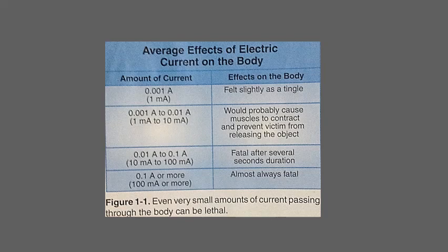Electrical shock. Electricity passing through a human body causes an electrical shock. The severity of a shock does not have as much to do with the voltage as with the amount of current. The shock of 10,000 volts is no more deadly than that of 120 volts. On the other hand, shock approaching 10 milliamperes or 0.01 amperes is painful and could cause severe injury.